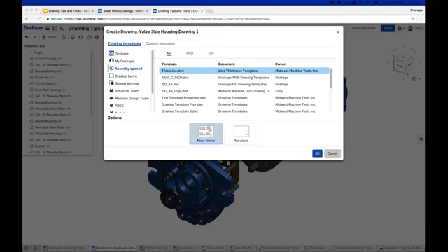Is there a way to dimension between a sketch line and a line in a drawing view? I need a dimension between the horizontal tangent of a radius and an edge of my part. You can insert sketches into the drawing view, and they are referenceable as selectable as dimensions, for instance. So I will show you that in just a moment. Can you add adhesives, thread locker, etc. to the bottom of the assembly drawing? No, not as of today, right?